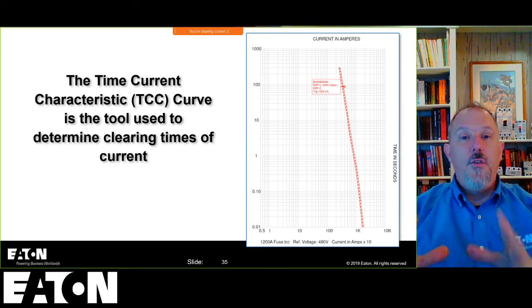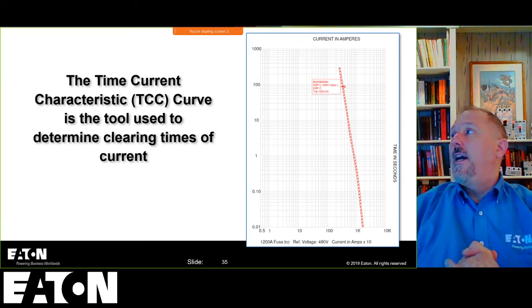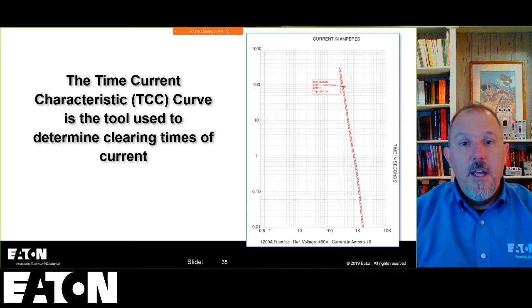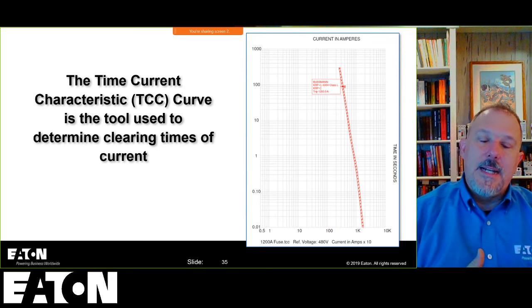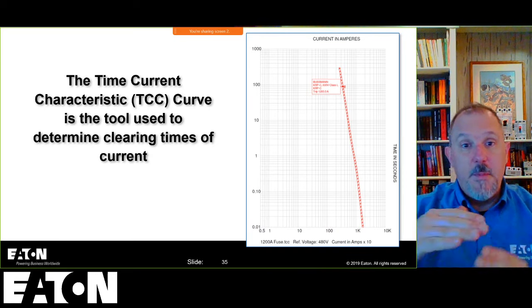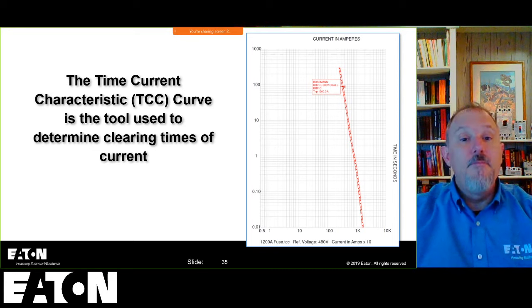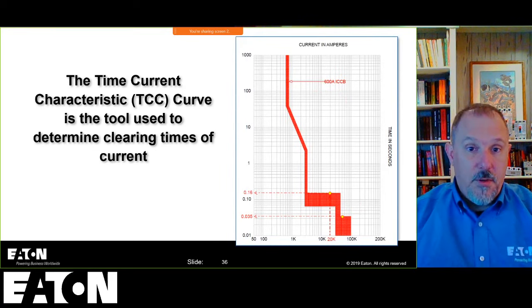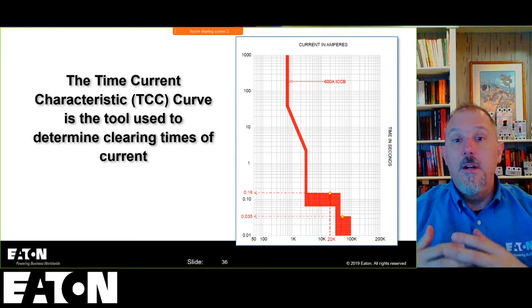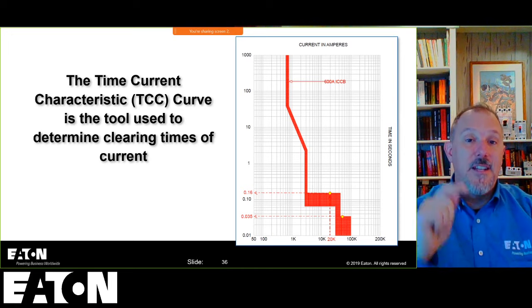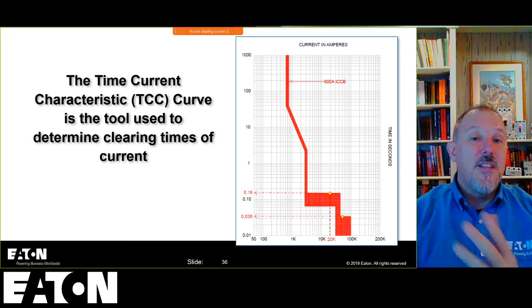Because if you, for example, this is a 1200 amp Bussmann KRP fuse. If you go, I'm going to go with a different size fuse, I'm going to go with the next size up, or I'm going to go with the next size down, that's going to change your incident energy calculations. And if you made that change because of your selective coordination needs, that's going to impact your calculations. Your trip units on your circuit breakers are programmable. You're going to need to know what are those settings, and those settings are going to be determined by your selective coordination.